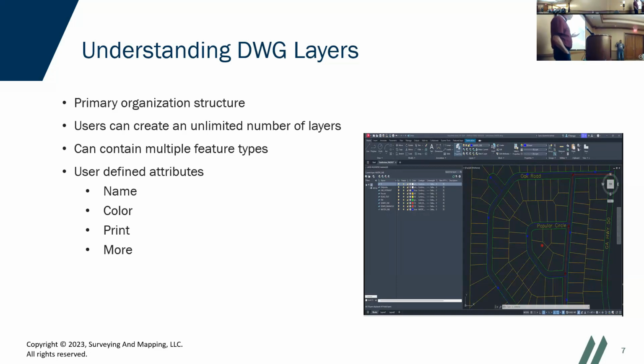A couple of y'all. So this is where you've got to be careful. I've seen cities and counties that will require engineers and surveyors to submit a digital version of their project in a DWG or DGN format. And they don't give you any spec. It just has to be in that format and has to be tied to the state plane coordinate system.